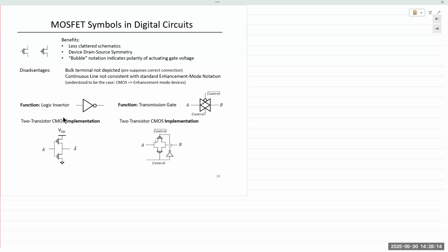So you have studied digital logic circuits for a while now. What do you think the bubble means? It is a PMOS, but the bubble means it's active low. So the bubble indicates active low. If you looked at the schematic of a digital chip and it says active low, or has a bubble, well, it needs 0 at that pin to be active. Absence of a bubble means it's active high, meaning you connect it to VDD.